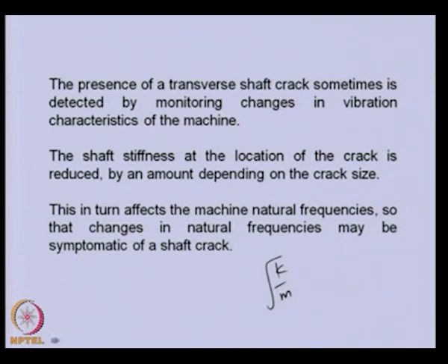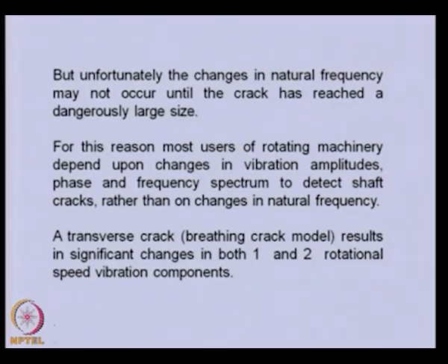So, that could be one indication of the crack in the rotor system, but unfortunately the changes in natural frequency may not occur until the crack has reached a dangerously large size. For this reason, most users of rotating machinery depend on changes in vibration amplitude, phase and frequency spectrum to detect shaft cracks rather than the change in natural frequency.